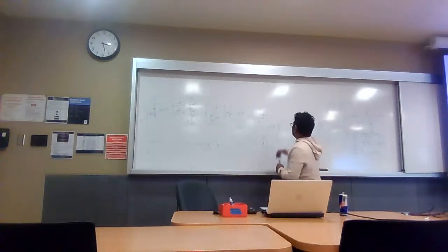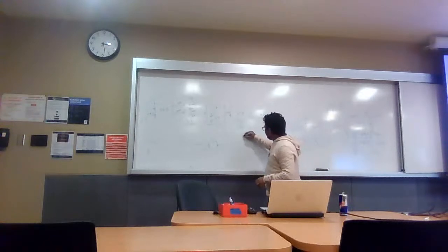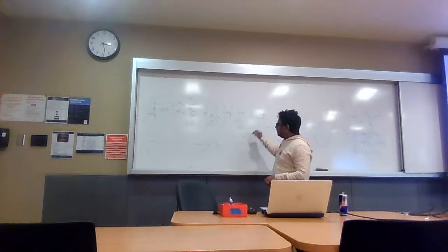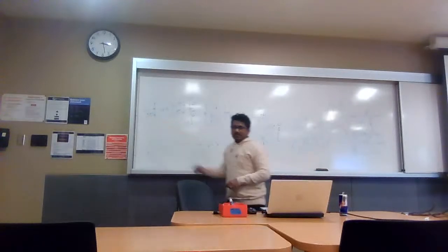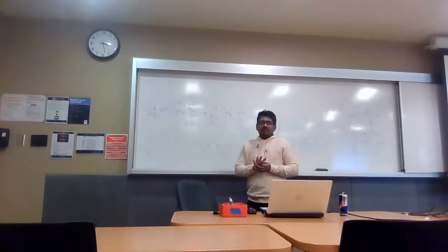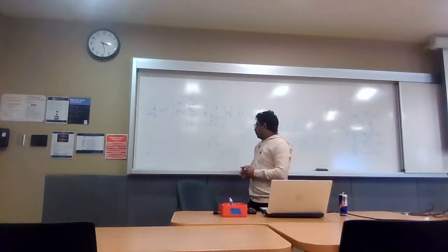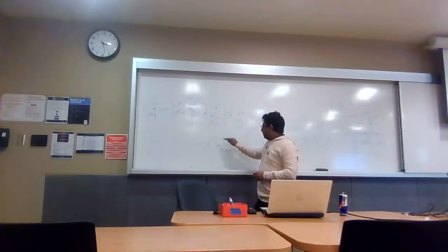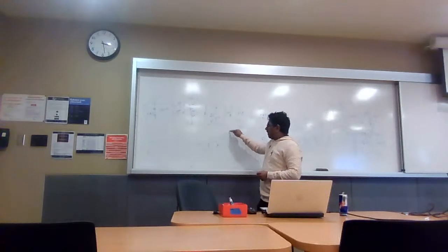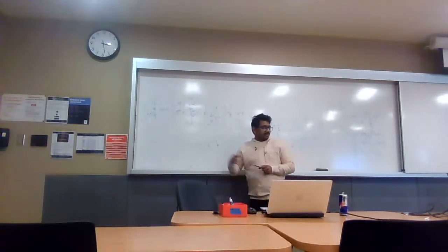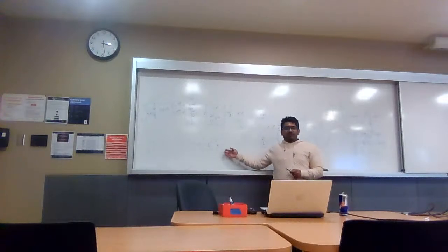Okay, I'm giving you a general formula. One is that we divide the feedback frequency by the reference frequency. If we divide this frequency by this frequency, then we'll find an integer value, and we'll find what the divider should be. And we can design this divider. We are familiar with the D flip-flop. We can design this divider using D flip-flops.